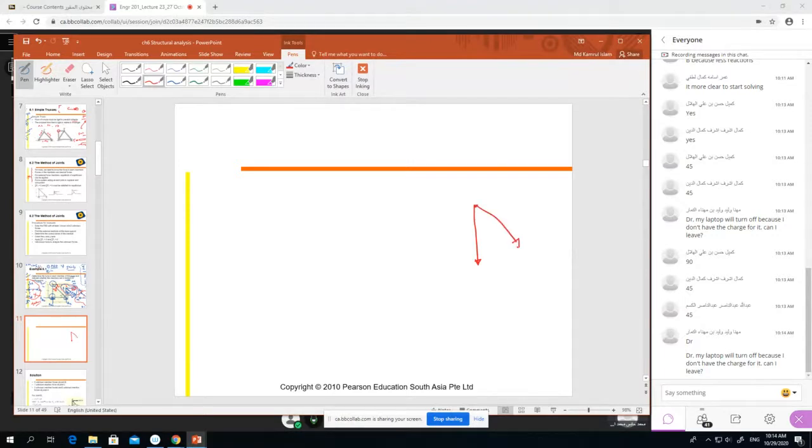So this is FBC and this is FAB, and here is a 45-degree angle, and here we have 500 Newton with 45-degree, right? This is joint B. We are analyzing joint B. Now we have two unknowns, so we use whatever equation you want to use.